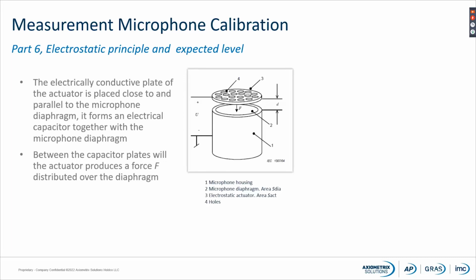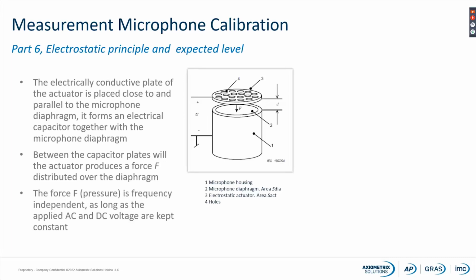Between the capacitor plates, the actuator plate itself and the diaphragm of the microphone, we produce a force which will make the diaphragm move. This force or pressure is frequency independent, as long as the applied AC and DC voltage are kept constant.